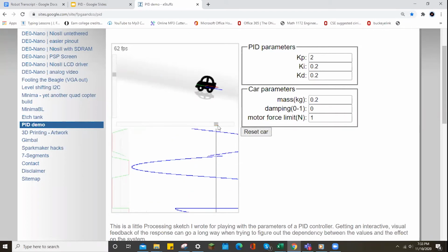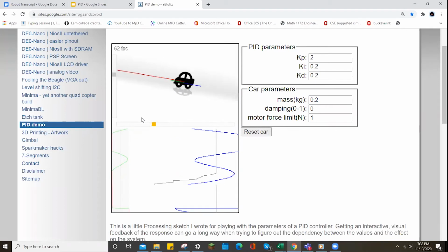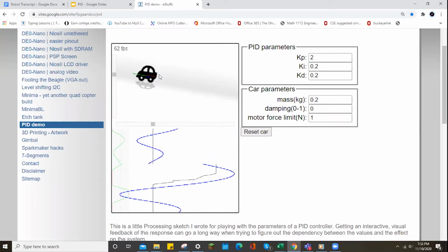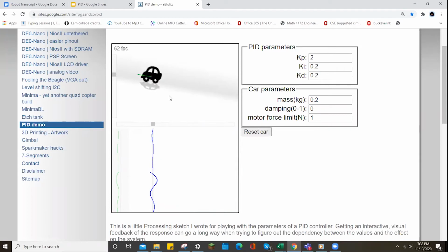we would see immediately, even with a small KD, that if you're moving up, you're not seeing the same level of oscillation. The KI calculates the constant error, accumulates it through integrals and pushes back up, but it doesn't necessarily account for the actual position where we have to get to and see that, okay, we're here now, we've got to stop.